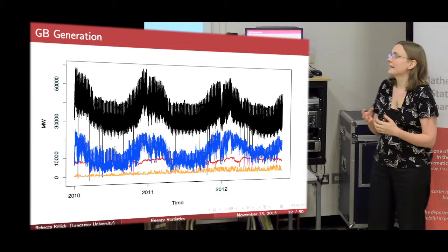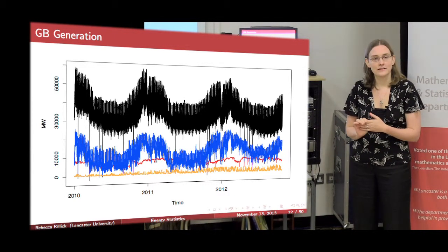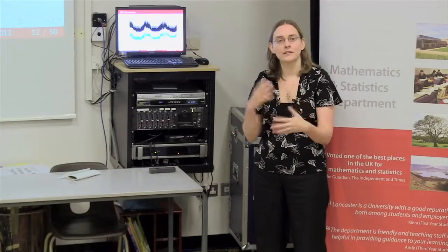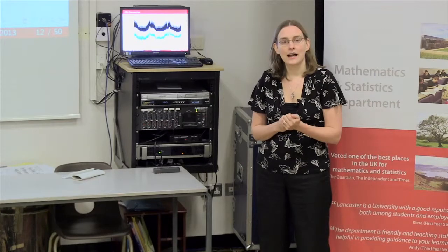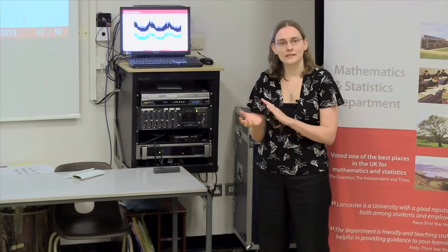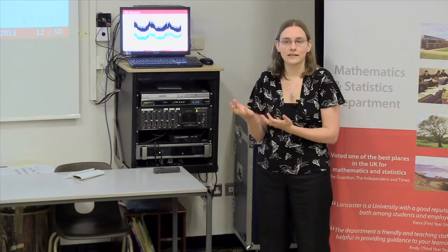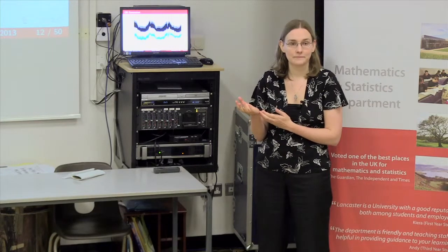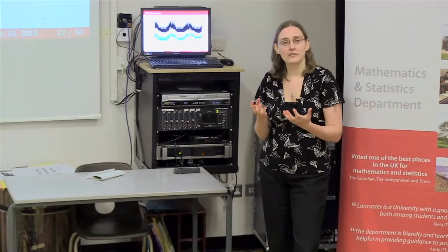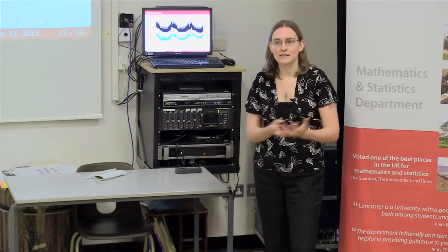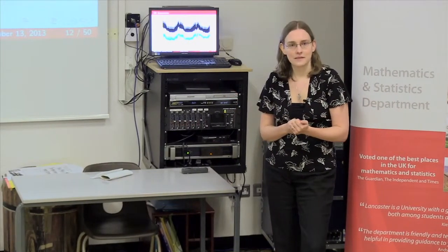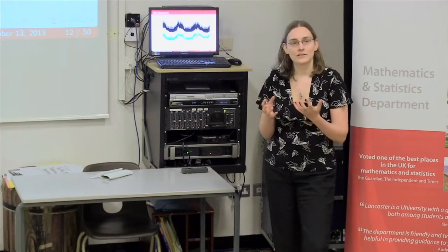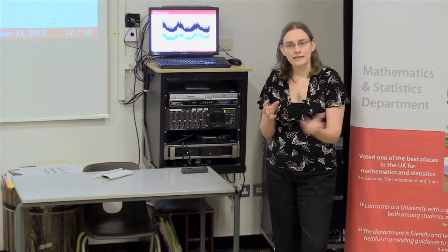And you can't plug that gap using the traditional methods because they take time to turn on and change the generation of the electricity. And we can't rely on the hydroelectricity because that's already being used to quite an efficient capacity. It's very expensive to create more hydroelectric plants because you have to find large enough reservoirs and there's time taken to build it. So the question now becomes, how do we actually bring in this wind energy?